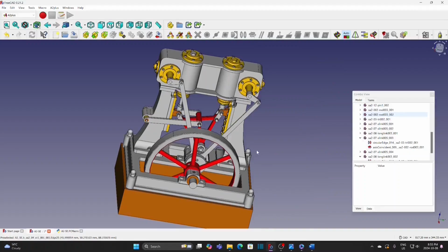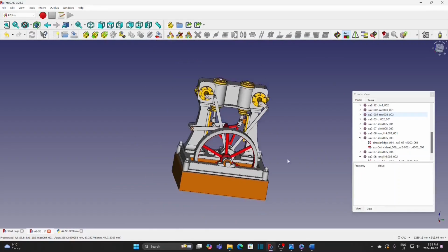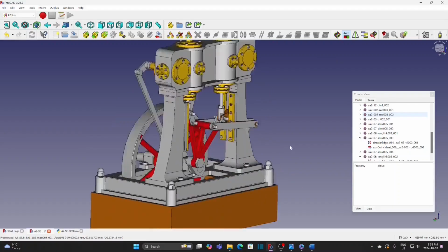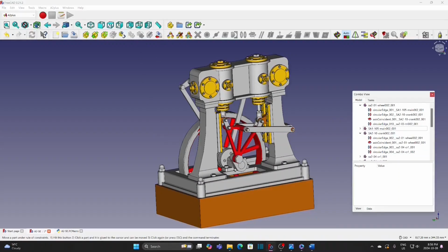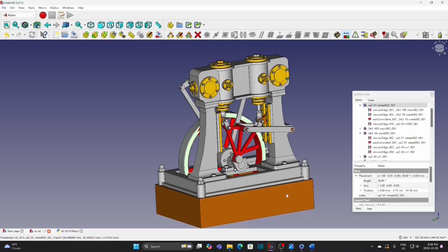Finally, the assembly is completed. Click the Move Under Constraint button and select the wheel. Rotating the wheel could move all the parts, but the response is very slow. A2Plus is really straightforward for assembling parts, but for animation, the response is quite slow when the construction is complex. You can see the angle under placement is changing, but very slow.